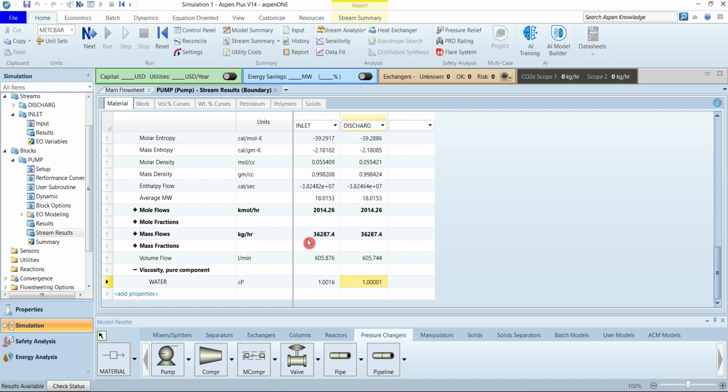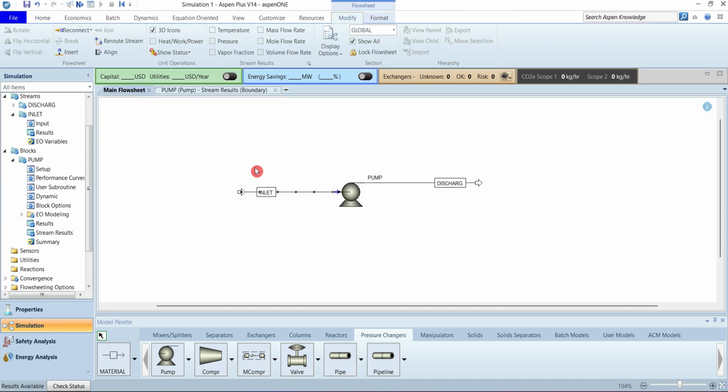In a future session, we will also work on developing the data sheet for the pump. One thing to notice is typically it's not important to define the discharge pressure of the pump. Rather, the purpose of the pump is to deliver a certain pressure in the downstream unit. Then, because of the pressure drop between the downstream unit and the pump itself, either from the pipe or the fittings or other minor units, including the instrumentation, a slight pressure drop happens between the downstream unit and the pump, and the discharge pressure from the pump should be higher than the required actual pressure in the downstream unit. So that is the subject of exactly the relevant case study. We'll come back to those case studies in the future sessions as well.